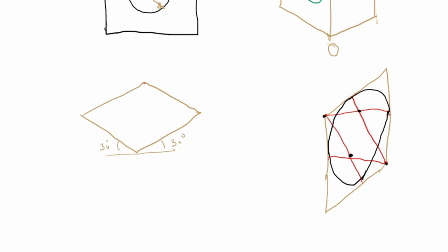So consider the shorter diagonal is this and this, midpoints 1, 2, 3, 4. From the shorter diagonal to this and from the shorter diagonal to this. Again from this corner of the shorter diagonal and like this. Now how many centers do we have? We have this point as center and we have this point as center. So with this as center, draw an arc, and with this point as center, draw another arc. Similarly, we have these 2 centers and complete this ellipse. Complete the ellipse like this.